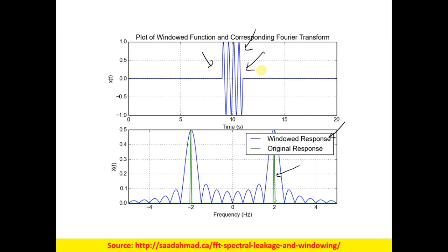because we talked about DFT and all these things, what we are doing? We are having a continuous signal, but we are truncating that because when we talk about 8-point DFT, we can take only 8 points, 8 components from the signal. We cannot take more than that. So we are basically abruptly truncating the signal, which is also regarded as the windowing.